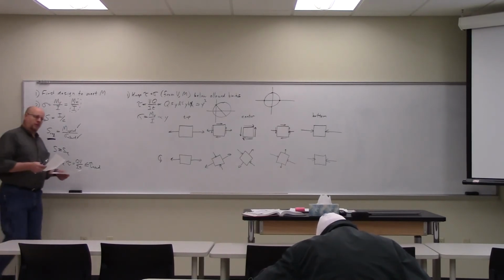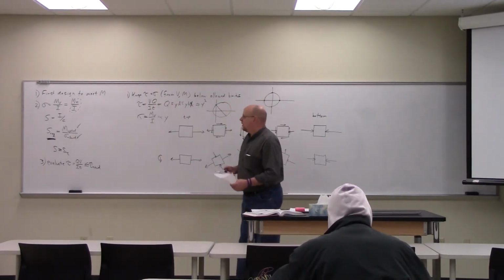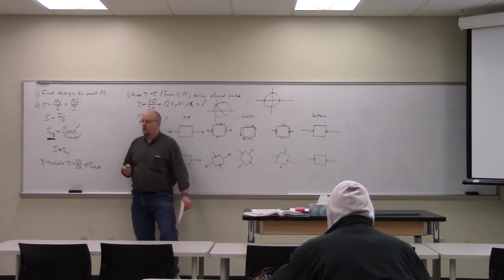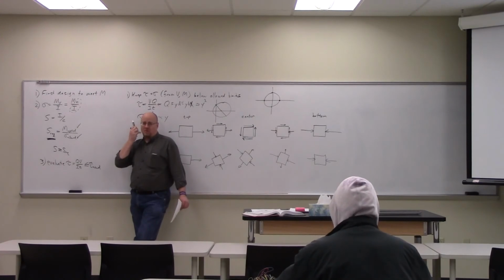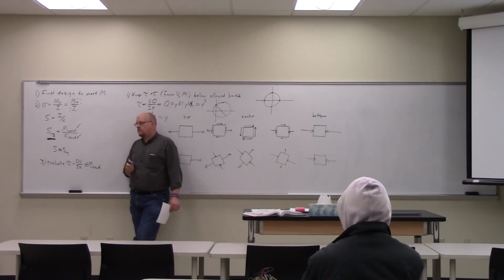So everybody understand that process then? We start with the moment, figure out what required modulus we're going to have. Then we can tabulate, we can calculate the required modulus, but the point is, you don't know whether you're going to use an I-beam, unless you know a priori, I have to use an I-beam in this application.